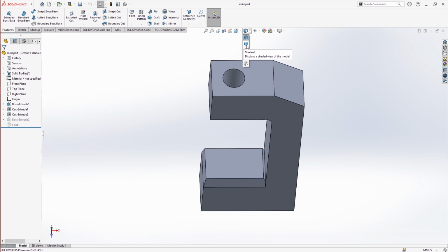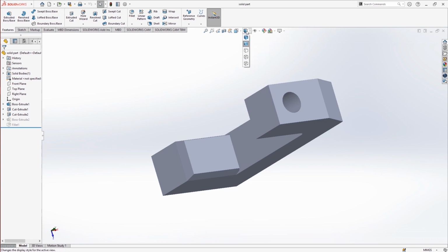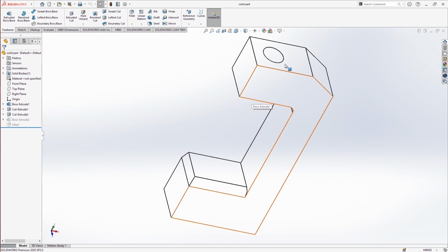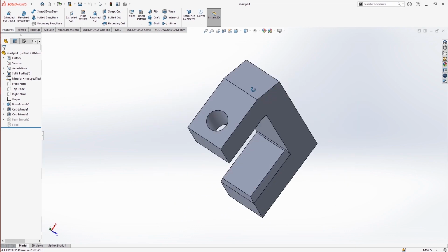What kind of view do you want? For example, in Edit there will be no corners, so here you can see the corners come in, and in this one in Edit there is no corner, there are hidden lines removed. You can apply it, you can just see these lines. And if you want to see the lines of the hole that it passes through, you can switch to this hidden line visible. You can see the holes. Hidden lines are in dotted mode. And the next is wireframe. So basically I prefer this shaded with edges mode because it gives a lot of detail.